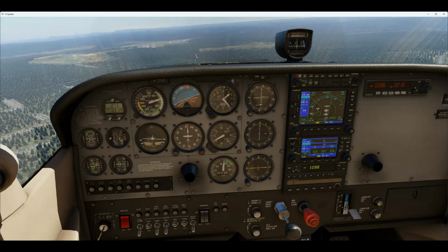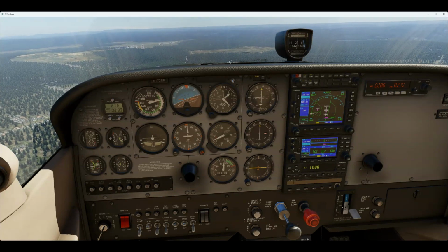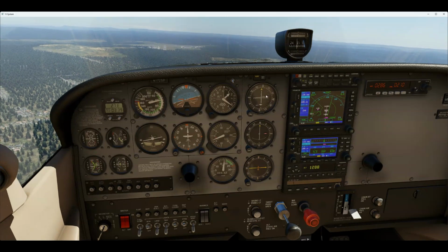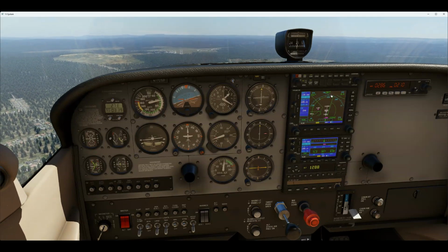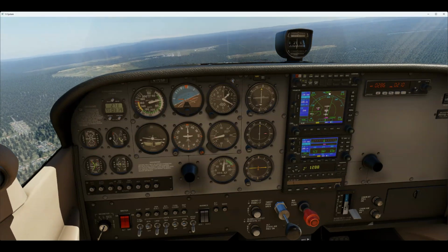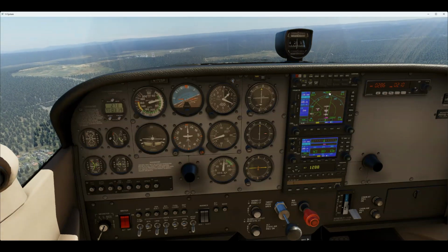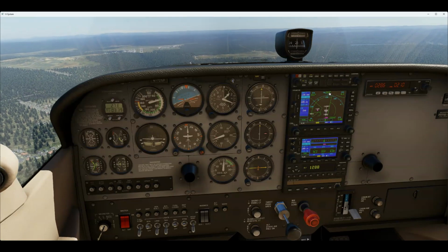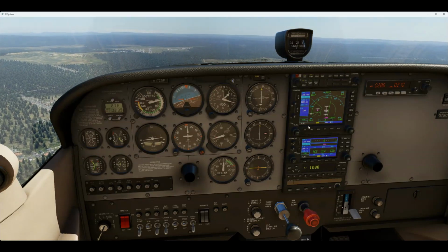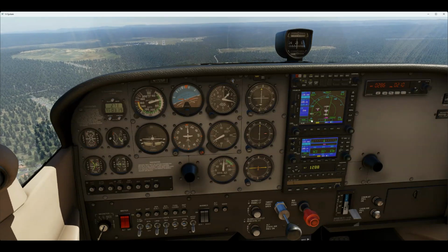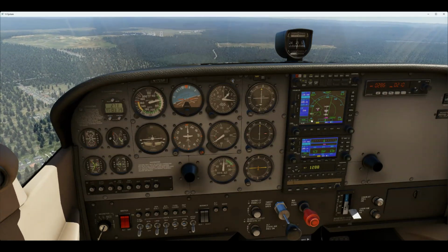Okay, we're almost captured again. And what I'm doing is I've kind of got a scan rate going, right? So I've got altitude, the CDI, and I'm also looking here to make sure I'm tracking in the correct direction. So there we go. We're back on descent rate. Ground speed now is 70, so we're going more like a 350 descent rate, roughly. We'll keep going down.